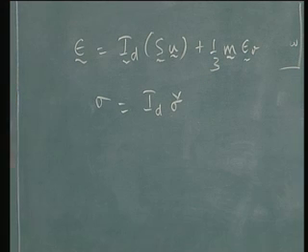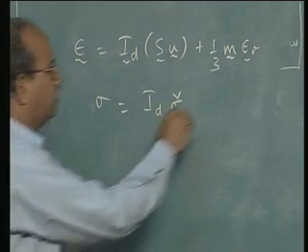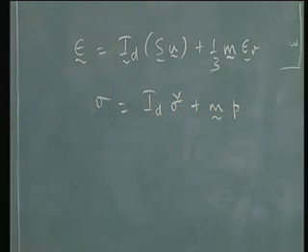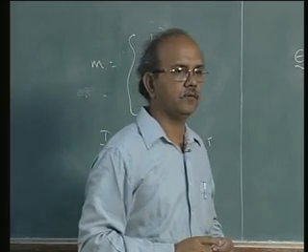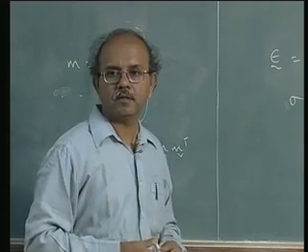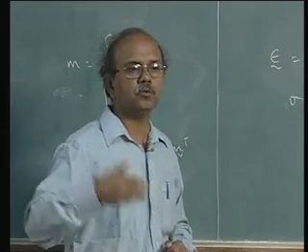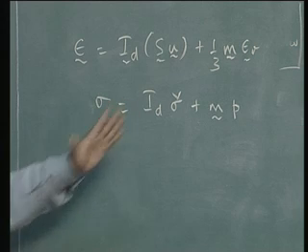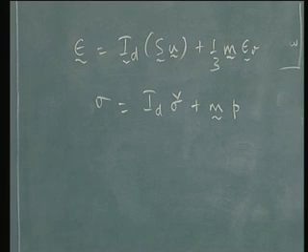On a board, when you want to write all the matrix forms, it becomes a bit complex. So sigma is again split into two categories, that plus m into p. Epsilon v, of course, you know, is epsilon 11 plus 22 plus 33, or epsilon ii. So again, sigma is split into two terms, the deviatoric term and the dilatational term.